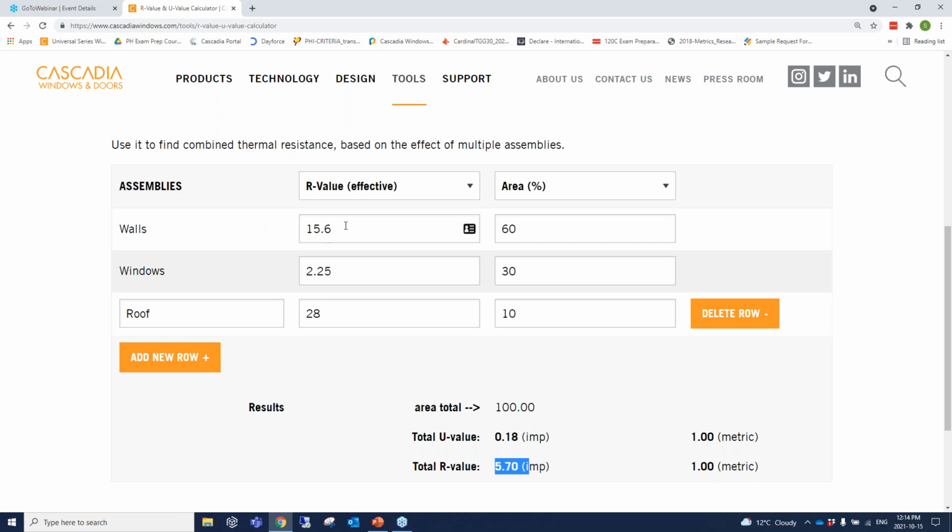Let's increase the wall insulation. Let's make it 10 times thicker. Oh, gee, okay, well, that only got us to R7, so that's not very realistic. We're not going to increase the thickness 10 times. How about the roof? Let's add some there. Well, you can add infinite insulation to the roof, and because it's already a great assembly, it's not going to get you much. It's already at the point of diminishing returns. So I'm obviously leading you to the windows.